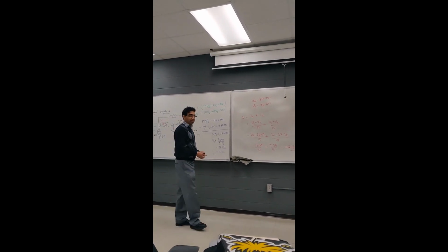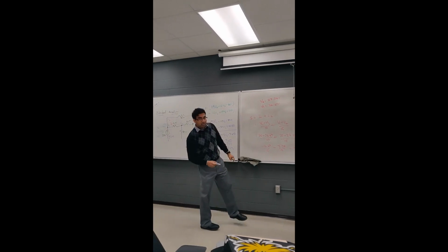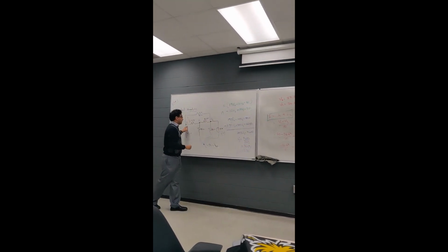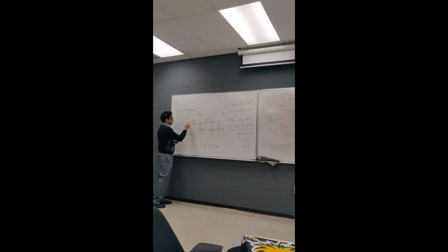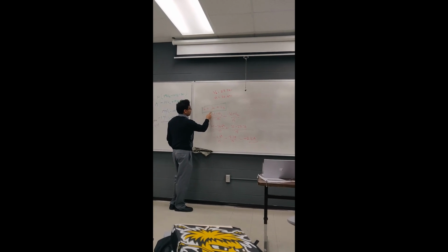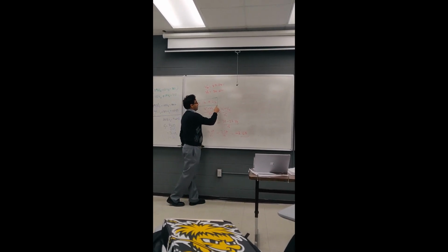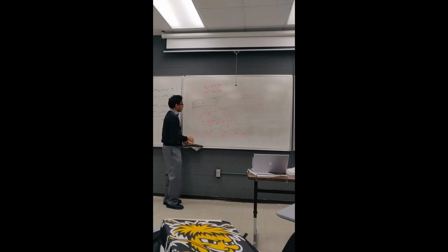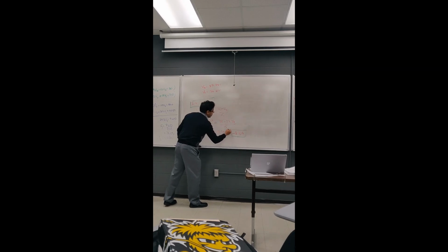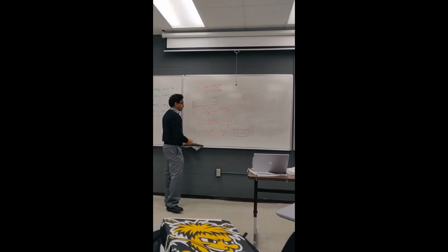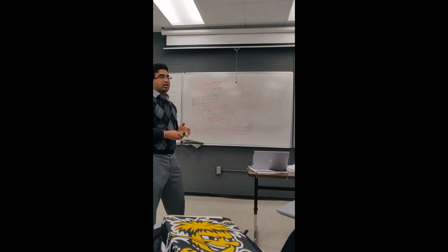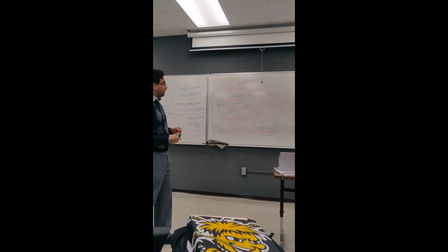Once I have the node voltages, now my goal is finding I. I'm assuming I equals I1 plus I2. Now I1 equals V1 minus V3 over 10, I2 equals V1 minus V2 over 15. Substituting those values, I end up with a negative number, negative 2.16 amperes. That's the total current. That negative indicates that the source is not supplying any energy. Instead of supplying, it is taking energy.